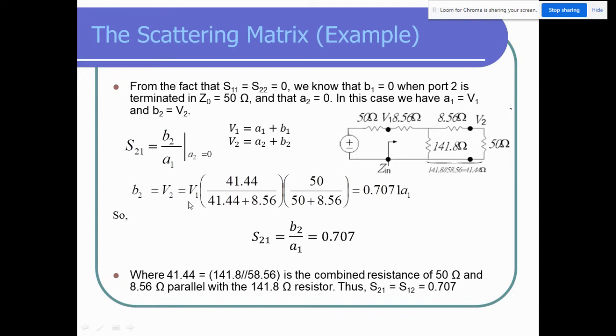So now we know that this whole voltage is here, isn't it? So now this voltage is the input of this network. To find out V2, we need to make another voltage divider across the 50 ohm, this with this. Since this whole voltage is here, we use 50 multiplied by the whole voltage divided by 50 plus this. So that's how we got this whole thing in terms of V1. As we know that V1 is equal to A1, we put A1, and if you calculate this one, you will get this.